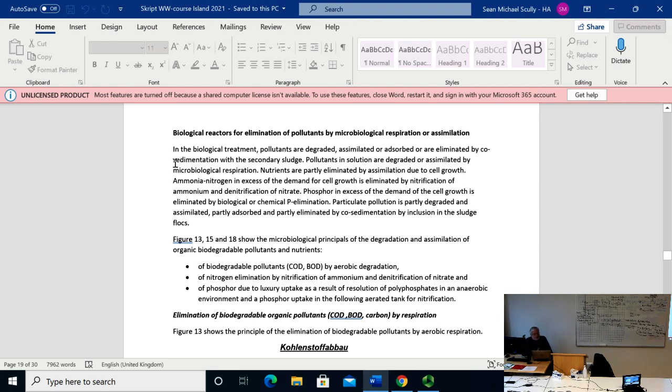In the biological reactors, you do not get purely dissolved pollutants, but you also have pollutants which are not settleable, but which are particulate. They are very fine particles that do not settle; you can eliminate them by filtration, and you'll find them in the effluent of the primary settling tank.